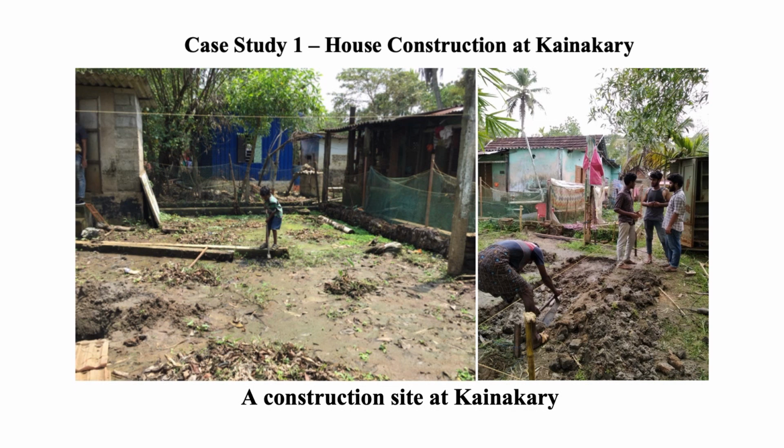Our task was to check the soil, whether it is good enough to have a building constructed, or what kinds of improvements we could make in the soil, and then to make certain protocols on how to design a structure and how to implement those design parameters. When the site was inspected, we noticed that the water table was very close to the earth level. We have seen a photograph of that in the previous segment also. The soil from the site was collected for testing. Different parameters were tested, including engineering properties and index properties, and then a protocol was developed accordingly.